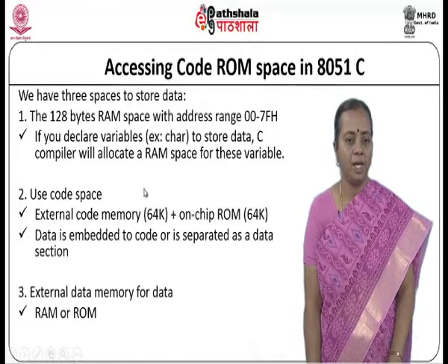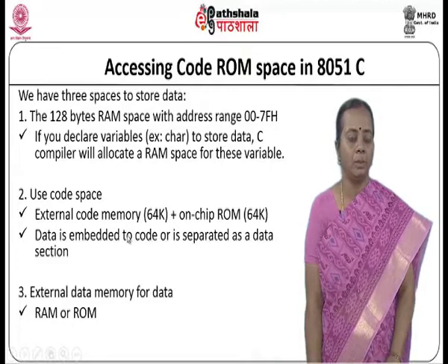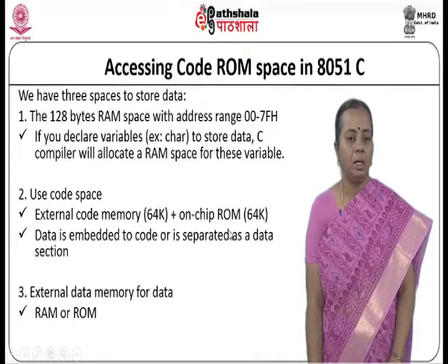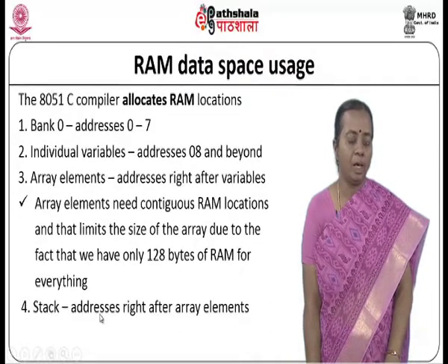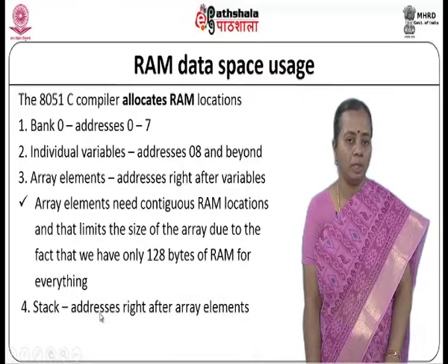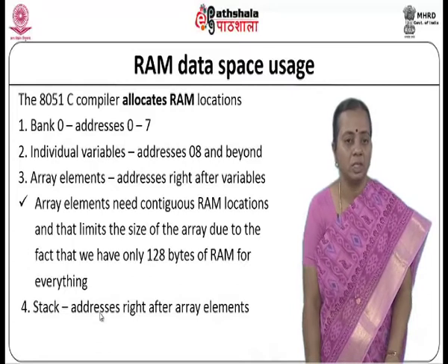Because the system has the code space, we can either use the code space on chip ROM, or I can use external memory. So, I can make use of external code memory, or on chip ROM, or we can use external RAM or ROM for accessing or writing data over there. This can also be controlled by us in the code declaration itself. If I change the declaration, then I can decide whether to write inside or outside, with the code memory or with the data memory. All those things can be controlled by the syntax we use in the declarations.